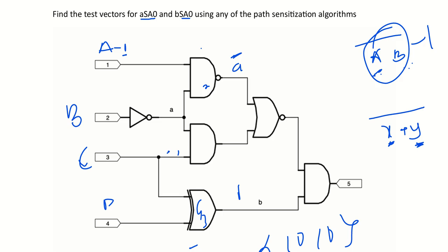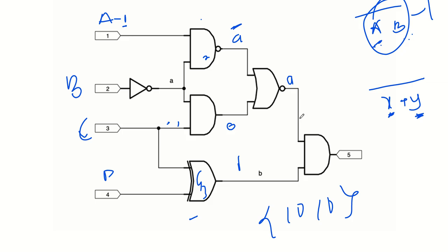Okay, so we always want one of them to go to 0, and it means that we have to let the lower one go to 0. So this circuit is assumed to be always 0. Now, if this circuit is always 0, then what will propagate here is A, because it will be A bar bar. So A. Then we come to our next branching point, and we have an AND gate.